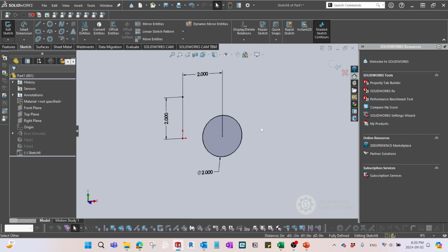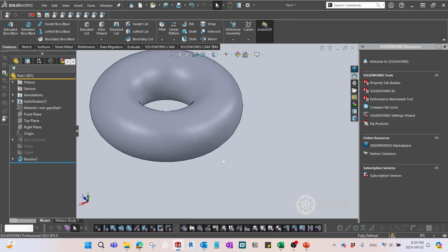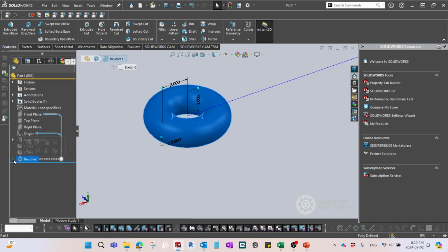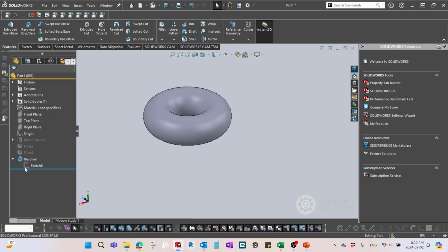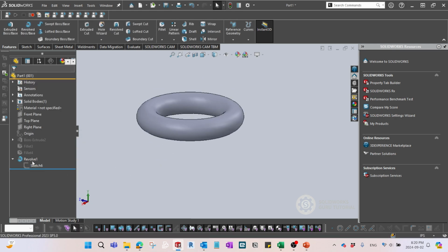And then I'm gonna go to the revolve. This is a little bit thicker, so you can also simply adjust the size by 1 inch. So we can simply create it with one feature versus 3 different features. I don't want you to create redundant or more features, because by creating only one feature you can achieve the same thing. So you can simply go with one feature item compared to the 3 feature items.